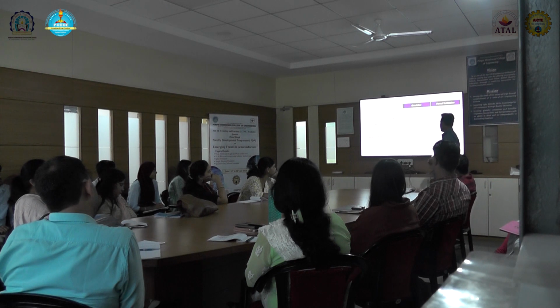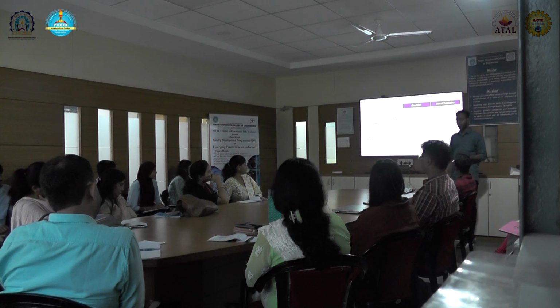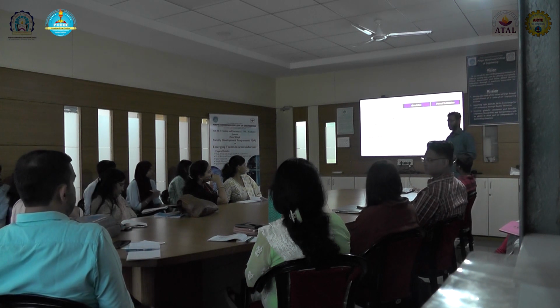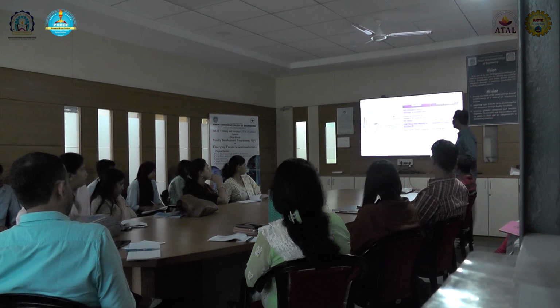In simulation, if there are any failures, we get to know it only at the end, after the whole transaction is completed. But in formal, we have the property, and it will point out the root cause of the bugs. We don't need to see the whole scenario. It will point out the root trace, and we can debug from there.